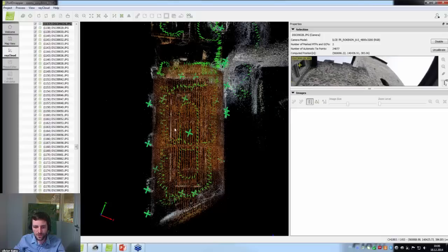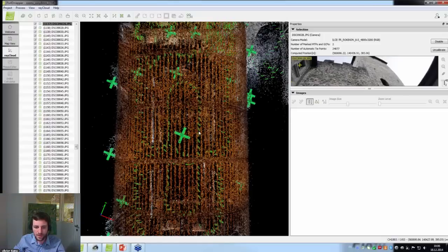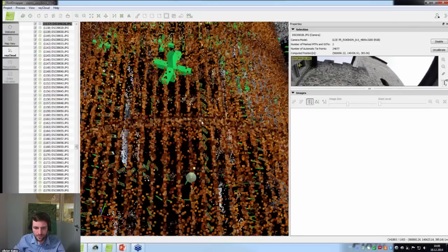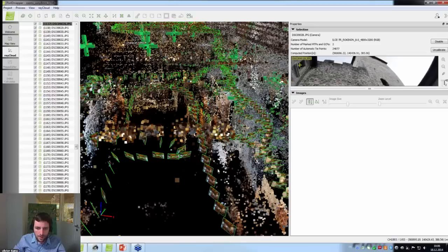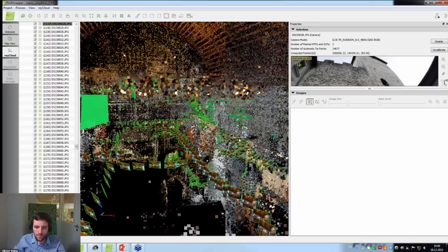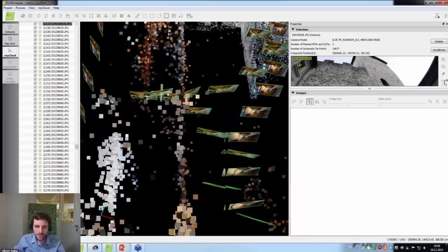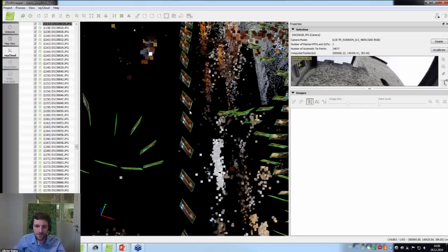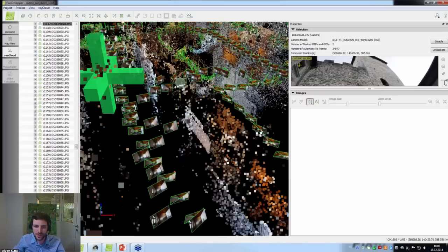And then we did another circle there in the middle where we were very close to the objects that were in the middle of that room. However, between the circles, we didn't do a big jump. So every picture is very close to another one, at about 50 centimeters. So you never have a break between the different loops that we did to do this project.